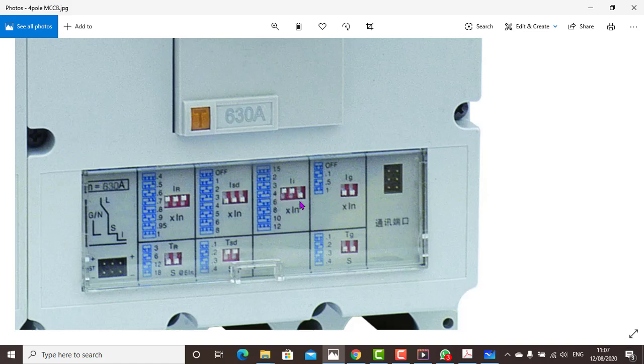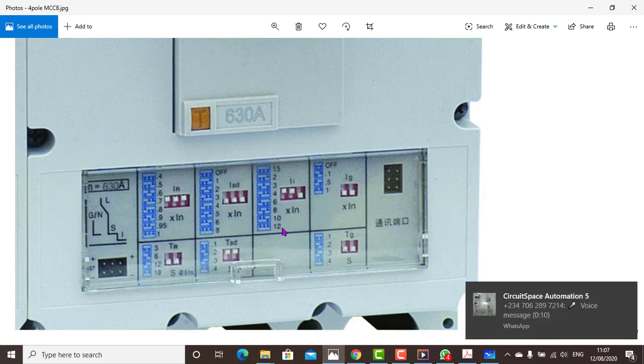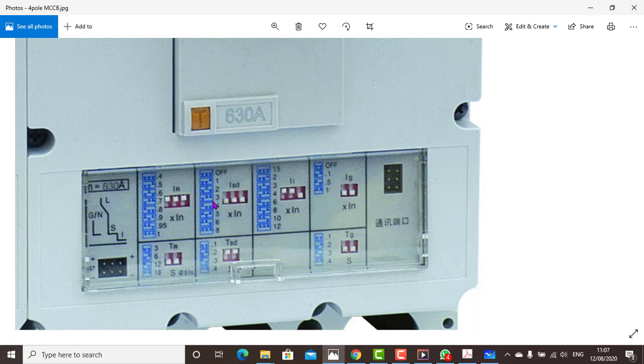But here, let's see what they set. They put up, down. Up, down is 2. It's wrong. It cannot be 2, because of this 630. In fact, this one must be higher than the long. Long is 5040. Short must be higher than that. So short will start from maybe either 10 or 12. It cannot be equal to long. If you put 8, it becomes equal to long. So it should be higher than the long. This is instantaneous, so it should be around 10. So you now have 6,300. You understand now? So that is it.